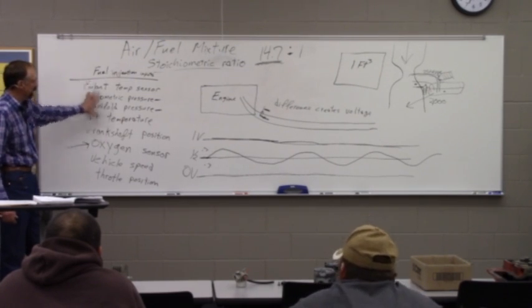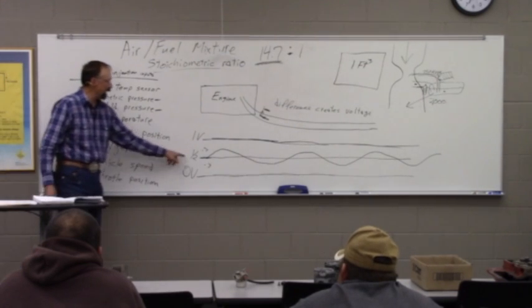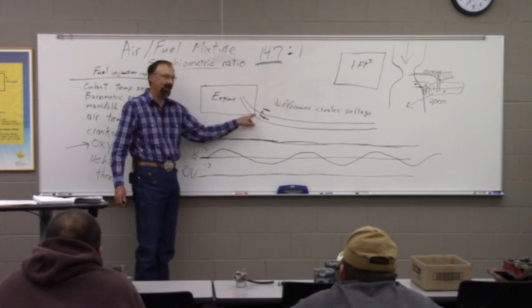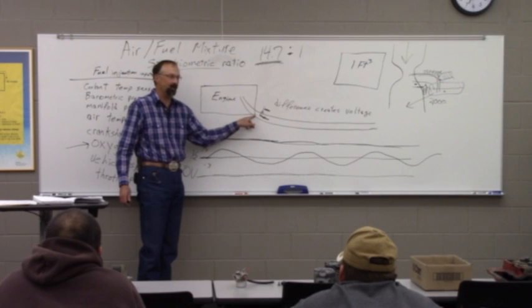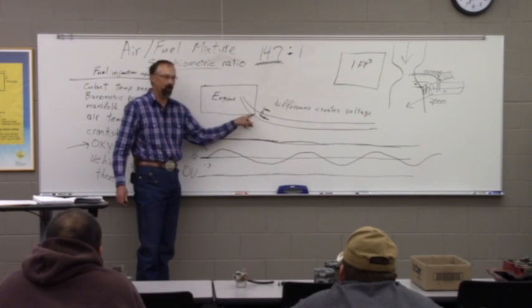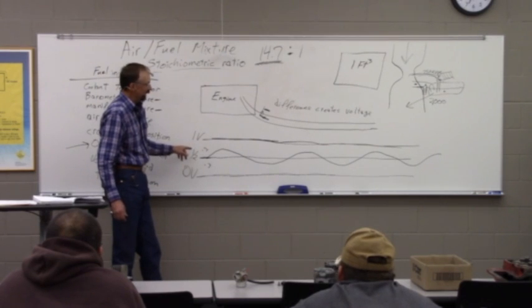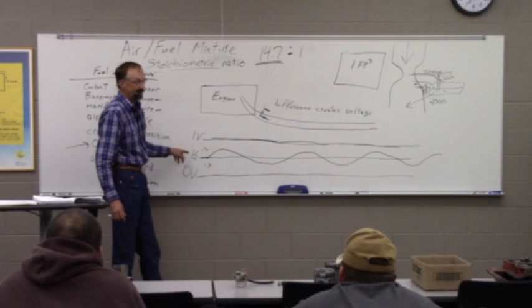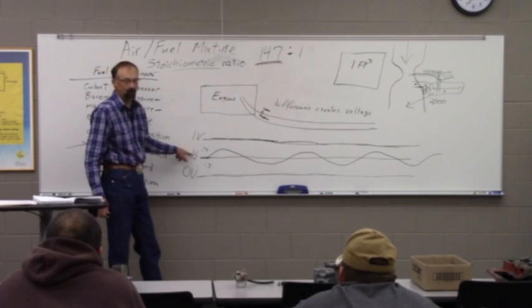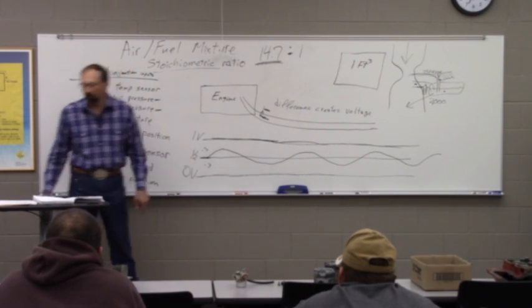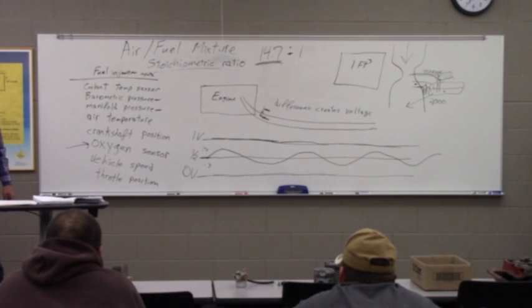But all these kind of were easy once we got a way to test how much oxygen's still in that exhaust coming out of our engine. To the best of my knowledge, there hasn't been any gasoline automobile manufactured in 35 years that didn't use these, because they're really useful in that fine-tuning process.